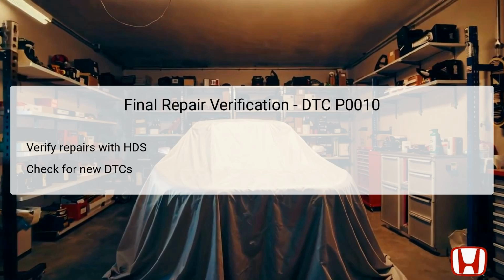By checking for new DTCs after repairs, technicians can validate the effectiveness of their work and confirm that no additional issues are present. If the HDS does not indicate any new fault codes, it suggests that the systems are operating normally. This process is vital for ensuring that the vehicle's performance has returned to optimal levels, further improving reliability and overall driving experience. Verification steps empower technicians to ensure that they have resolved the root cause of the problem and not just treated the symptoms.